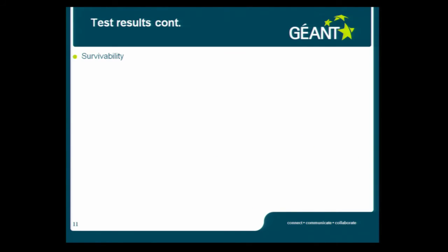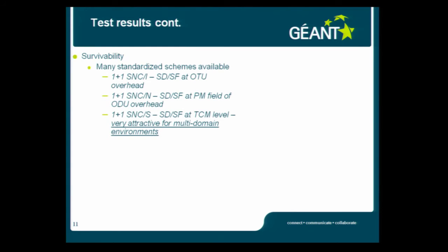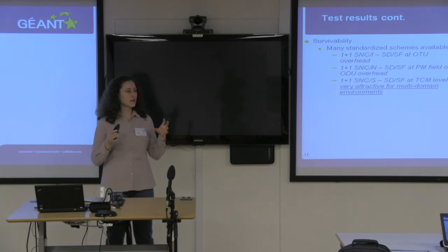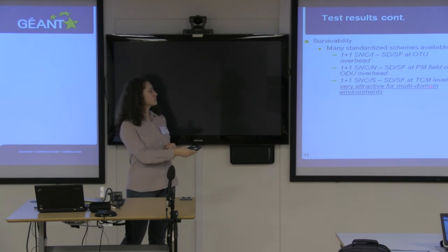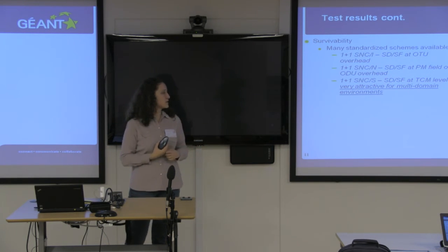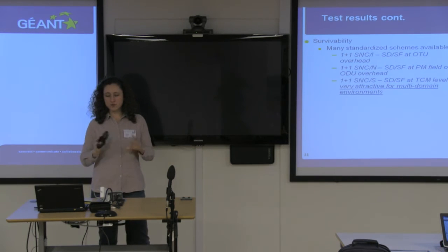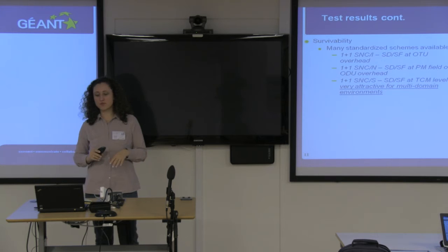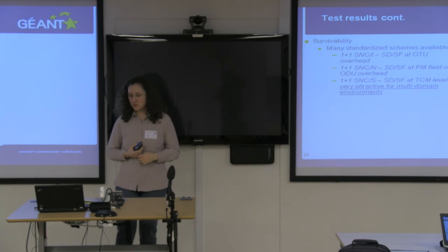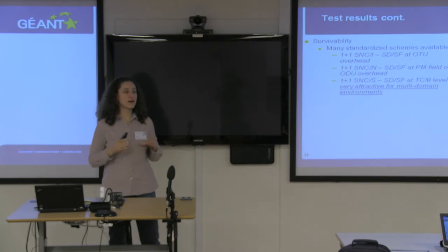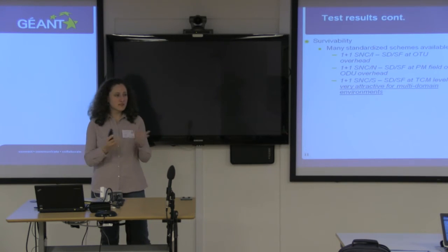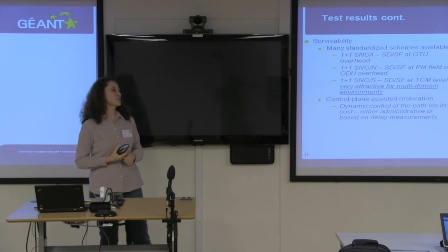So the next test that we did was survivability. It was very interesting to see many different standardized schemes at the ODUk level that were shown. The most interesting one, of course, was the one based on TCM, tandem connection monitoring, where the tandem connection monitoring was actually providing the signal failure and signal degrade alarms. So for multi-domain environments, I will probably tell this 20 times until the end of this presentation, we're very excited about it. It really provides true multi-domain operation, as could be seen.